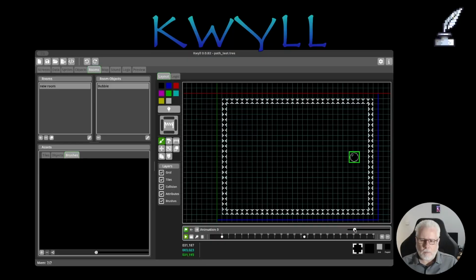And you can have multiple animations on an object. So this bubble has 2 animations. One does an upside down V, and then there's a simpler one with just 2 keyframes, which just moves between those 2 keyframes. You can have as many keyframes as you like, and it can go on quite some time. So you can create complex animation sequences and sets of them in the animation editor. Moving them is as simple as going into record mode, moving the object, and inserting a new keyframe with the key button.